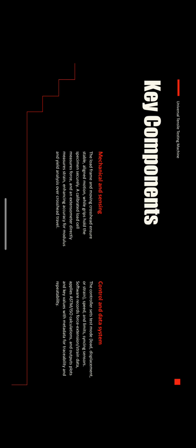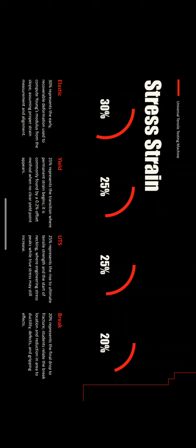The controller sets test modes, load, displacement or strain, speed and limits, sensing sensors. Software records force, extension or strain data, applies ASTM and ISO calculations, and outputs plots and key values with the metadata for traceability and repeatability. Stress strain.